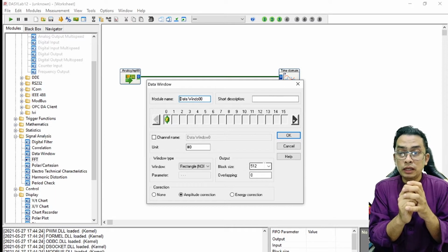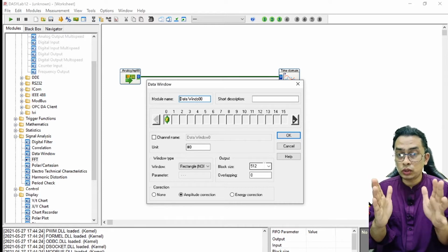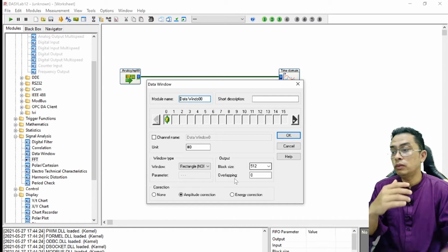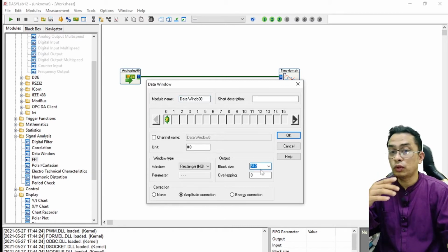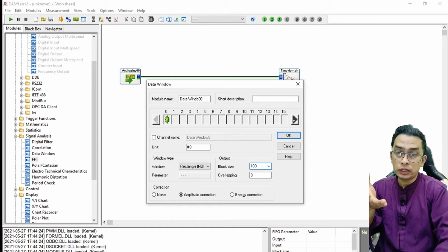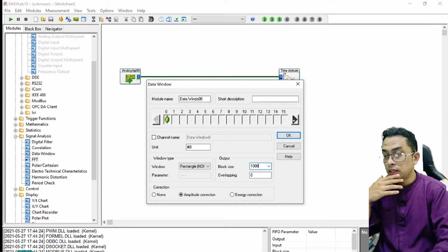Just picking a few points and converting them to the frequency spectrum would be an inaccurate representation of the frequency, so make sure that you choose all. We have a 10,000 block, so we choose 10,000 here, so that you can calculate for the whole block, and it can give a more accurate result when we convert from the time domain to the frequency spectrum.